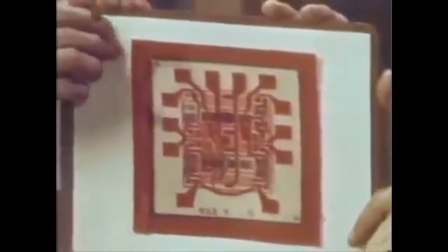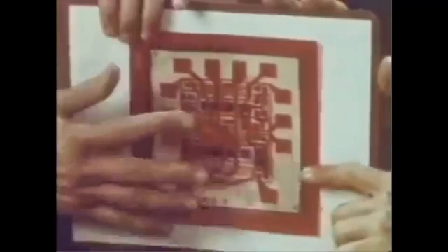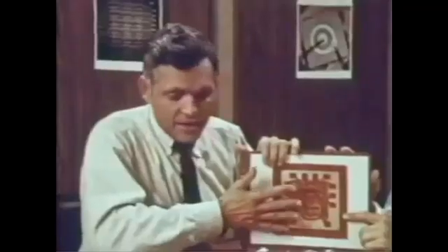Now, the artwork which I showed was only one mask, potentially. Here is the artwork in reduced plastic overlay version, which goes with a complete set to make an integrated circuit. There are 5 to 7 or even more of these potential masks. All of these must align carefully and precisely. These then will be translated into another set of glass masks, which will then be used for contact printing directly